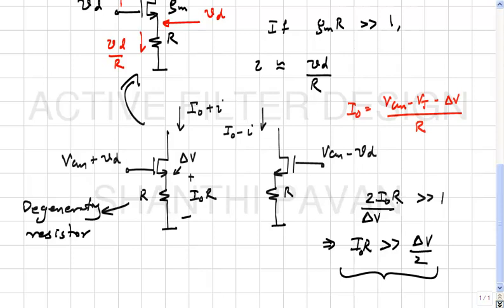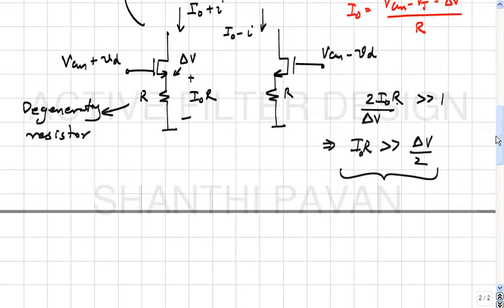Okay. All right. Now, what do I think? So is this okay, or is there a problem with this, or is there no problem? Yeah. So what about the common mode gain? Same as the differential mode gain, because if I yank both the input voltages by the same amount, the incremental change in the common mode current is again approximately 1 by R times the change in the input common mode, correct? Because it's got no common mode rejection. You understand? All right. So going by prior experience, what will you do to fix it?